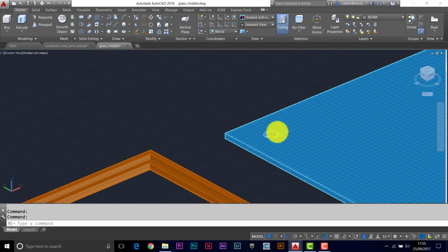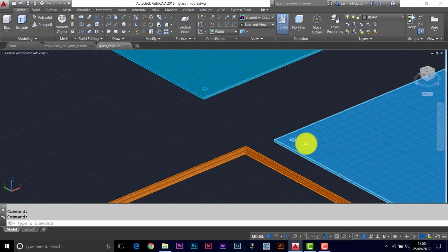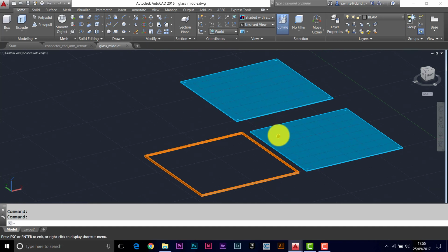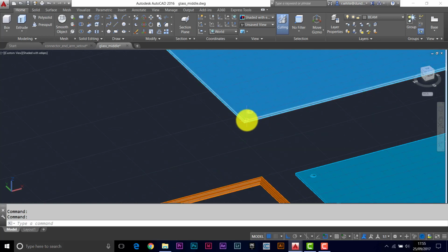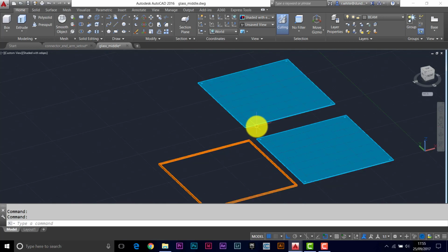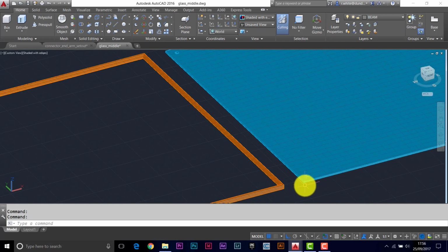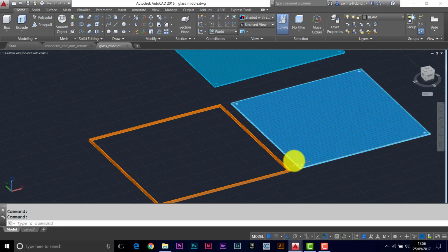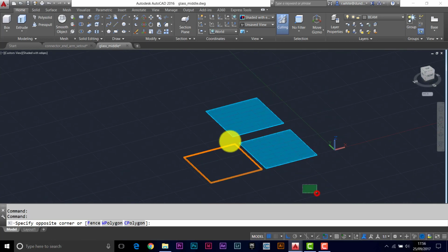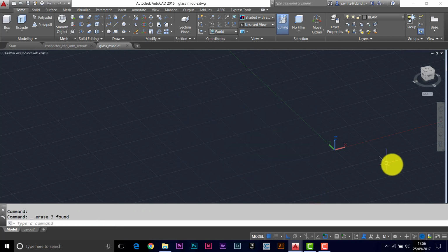When you cut a circular shape out of another object, what we can't see is the triangulation that's going to go on here. There's thousands and thousands of triangles that end up getting generated instead of just a simple plain surface. So usually when I'm advising students, I say keep it simple, just use a single plane for glass. But in a model where you're getting very close to the construction, you do need more detail. So for this one, we're not producing everything, but we're producing a lot more detail than I normally would. So let's build this up from scratch, and you can see how it goes together.